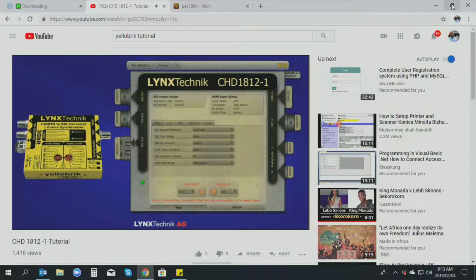And that means the device sending us an HDMI signal is going to basically ask us, gee, what's the highest resolution that you support? And we answer back and say, well, I can go all the way up to 1080p 60. And the sending device goes, great, and it sends us a 1080p 60 signal that will correspond to a 3 gig 1080p SDI output. Now, if you're using the module in a 720p plant or some other application that isn't 3 gig capable, then obviously that's a problem.